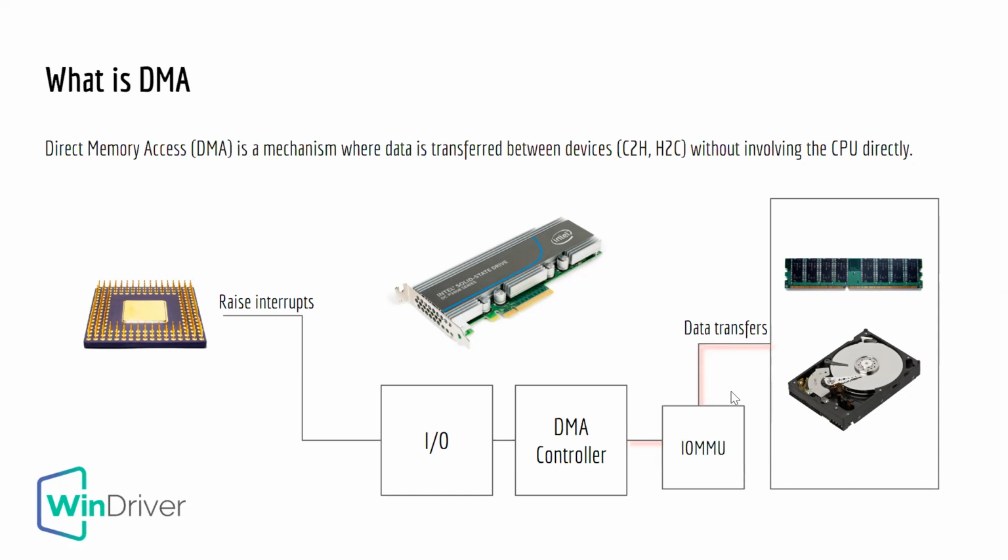Another component, and this is interesting, is the IOMMU. It's the Input-Output Memory Management Unit. So this component acts as a bridge between the DMA controller and the system memory. It functions similarly to a memory management unit used for CPU memory access. It translates virtual addresses used by the DMA device into physical memory addresses, and